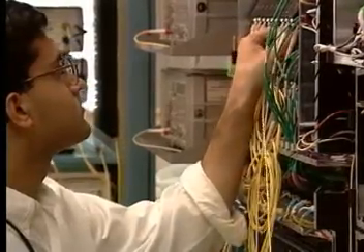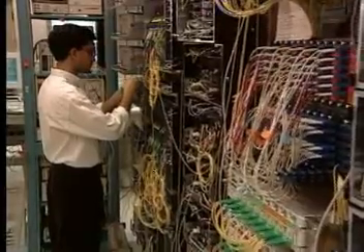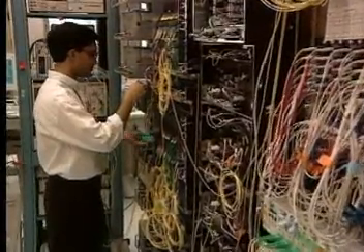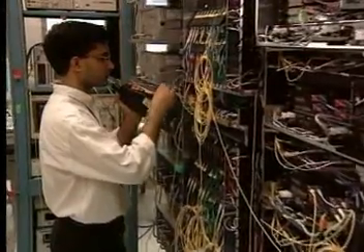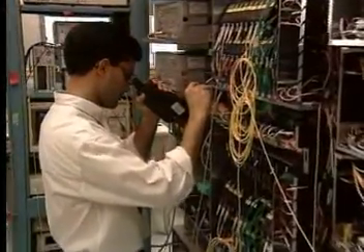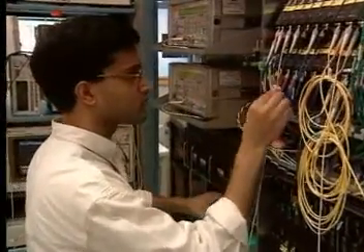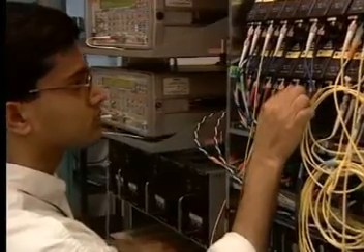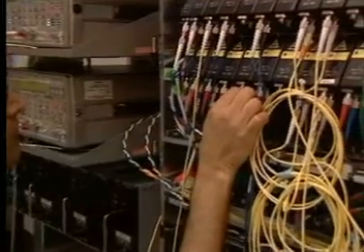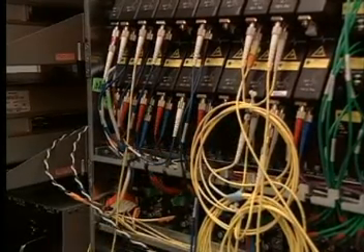Oily residues can also cause high reflectivity at connectors, which can show up as increased bit error rates in high-speed systems. DWDM systems are extremely sensitive to even minute amounts of contamination. What is worse is contamination, such as oil residues, may affect some wavelengths more than others, so the technician may suspect a problem in individual transmit-or-receive circuits when the real culprit is a dirty connector.